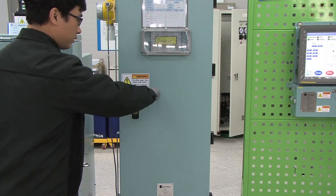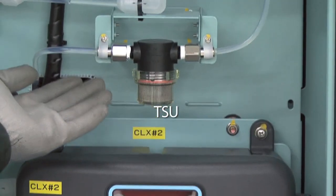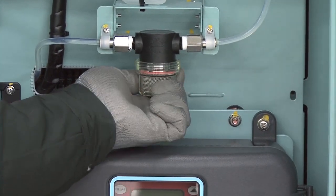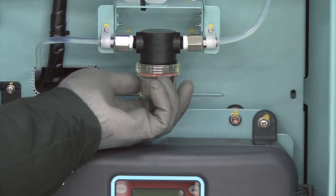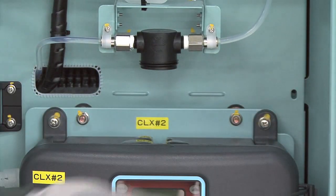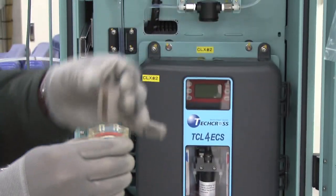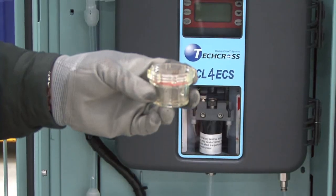Two. Regular maintenance. 1. TSU 1-1. Cleaning CLX filter and check leakage. Step 1. Disassemble the filter by turning to the left. Step 2. Drain the water from the filter and clean it with compressed air, 4 to 7 kilograms per centimeter squared.